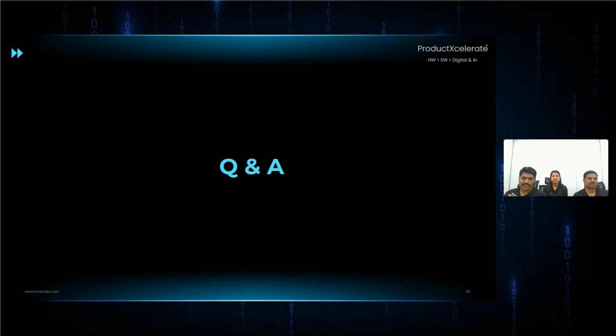Secondly, when it comes to defense, for the PCBs falling under the mil grade, we need to follow MIL-PRF Group A and Group B constraints for the PCBs. And for the end application of the products, we have to comply with MIL-STD-810G and 810H. And from the power and vehicles perspective, we have to follow MIL-STD-1275, wherein temperatures can range from -55 to 125, in harsh environments.